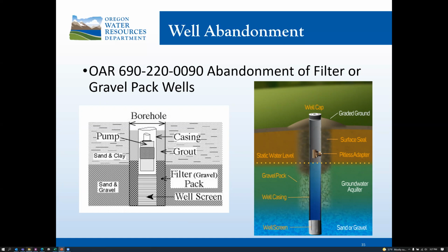As you can see in these diagrams of filter pack or gravel packed wells, the intent here is to ensure that that grout applied under pressure is able to effectively migrate out into the filter gravel pack and effectively prevent vertical movement of water in that screened interval.